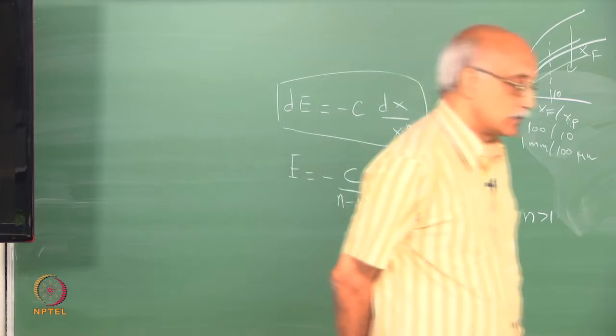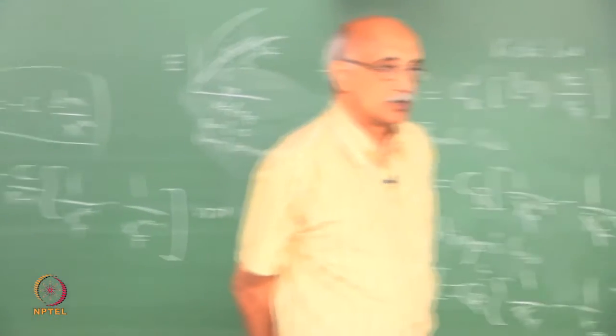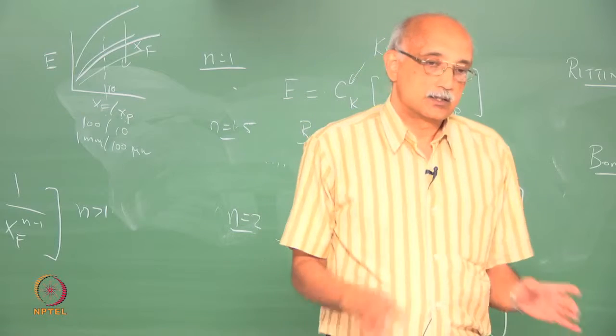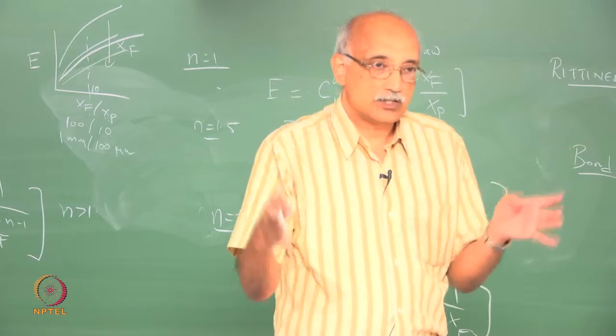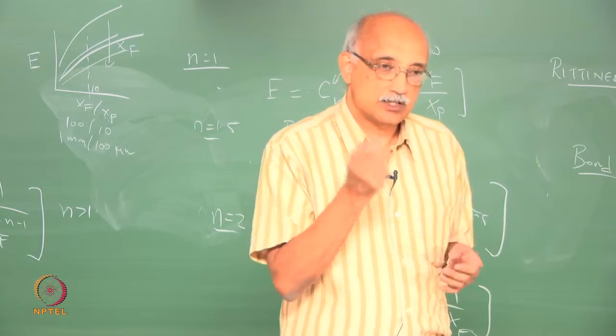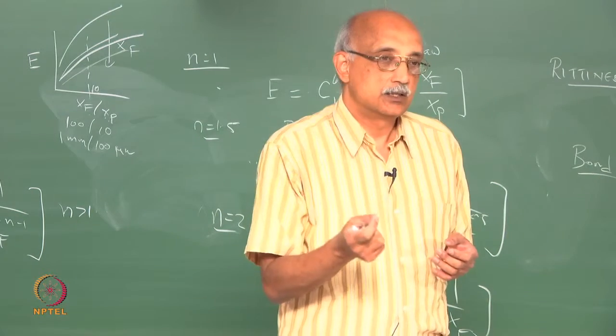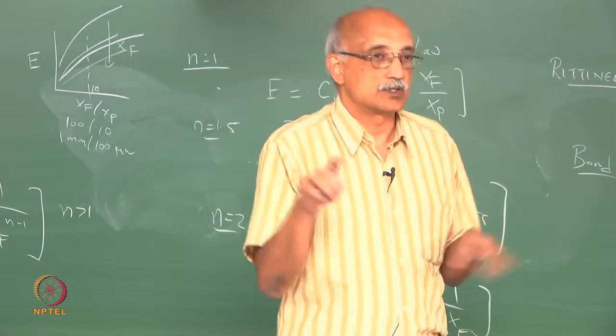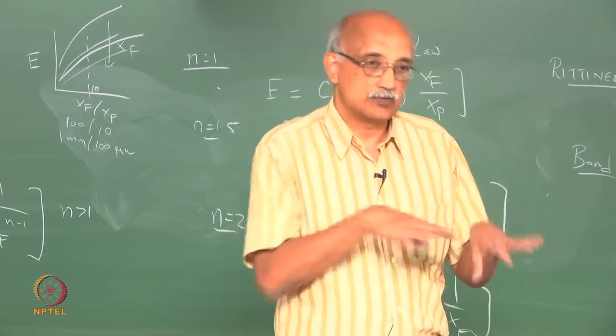See, when you look at surface energy, there are two components to it. One is the surface energy increase associated with the increase in total area, and the other is the surface energy increase per unit area because of excess energy built up. So the second parameter has to be minimized, but the first parameter should be maximized.